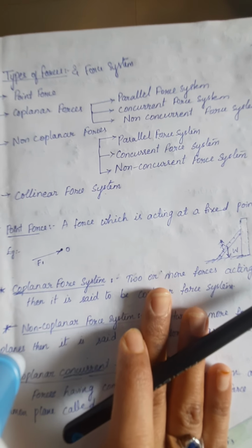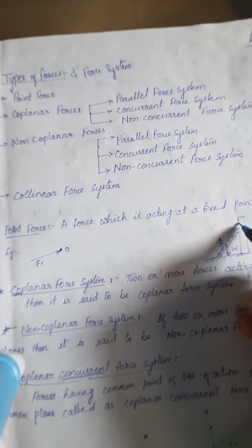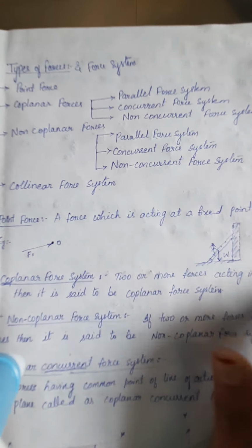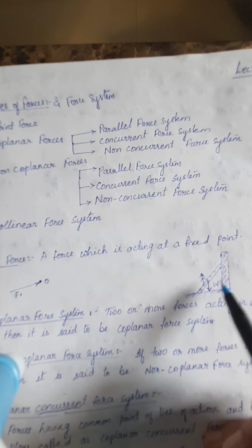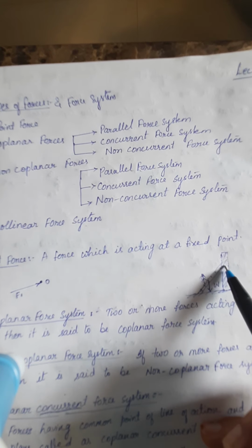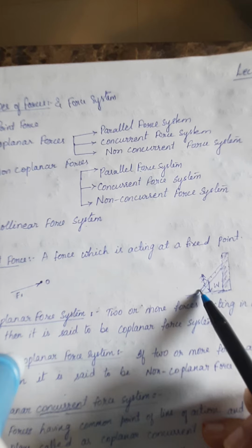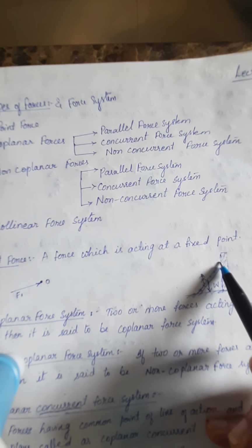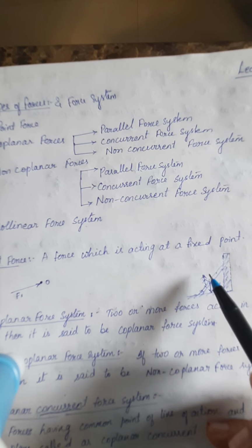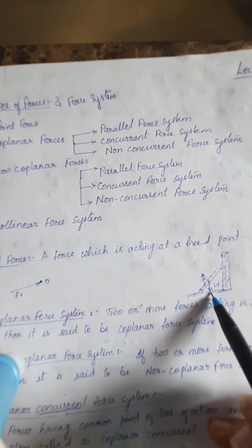For our numericals, usually you will get a problem of a wall and a ladder, and here it is a practical example of a point force. Whenever a man is climbing a ladder which is resting against the wall, and the man is moving from lower to higher position, even though his position is continuously varying, his weight is assumed to act as a point load towards the ground surface.